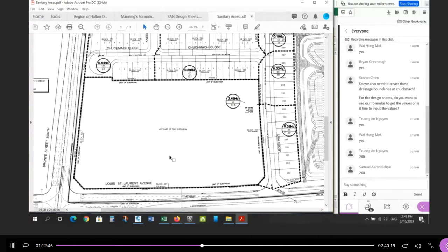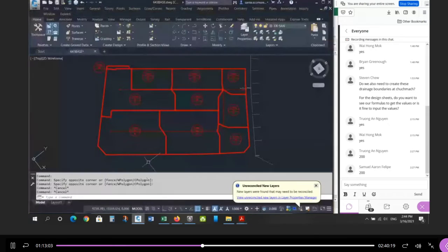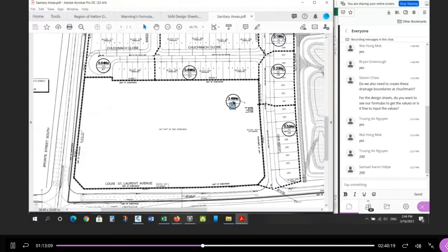So you'll see that when you do the calculation, right? You can compare your population to this 315 for the total and notice that it's significantly smaller. Okay, or you can do the math now if you want, right? You can go through the calculation, just add up your total populations for all these bubbles and see that it compares to 315. It should be a lot less than 315. So intuitively, you can kind of estimate what the difference is, but you really want to compare flows. What's the flow right now in this pipe expected, and what's the flow expected after we change this to residential? Okay.